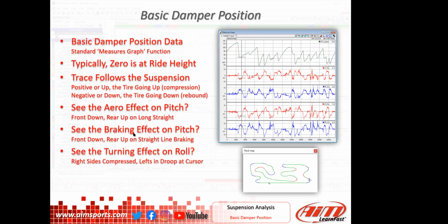Again, I just want you to get this basic damper position, a feel of what we're seeing. The next thing is the driver comes up there and dynamites the brakes, getting ready for turn one, starting into this left-hander. Look at what happens, and we'll see it in full size here, maybe a little bit more, but you'll see that the left front, all of a sudden, the tire gets packed up into the wheel well a little bit, just for a split second. The right front is doing the same thing. It gets packed up in. The rears, the tire is dropping down and dropping down.